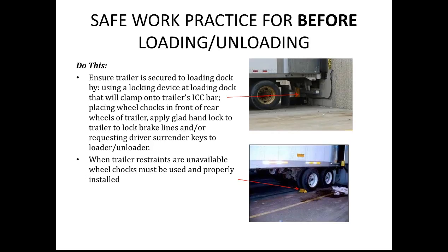Another method of isolating it is to apply a glad hand lock to the trailer to lock the brake lines, or to request that the driver surrender the keys to the loader unloader and put it on a pegboard. So these are four methods that you can use to isolate the equipment at your loading dock to make sure you don't get premature pullout.